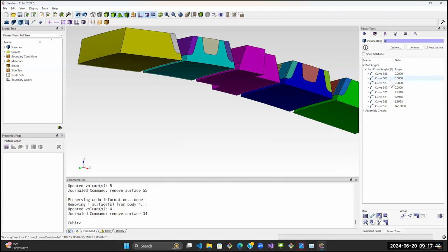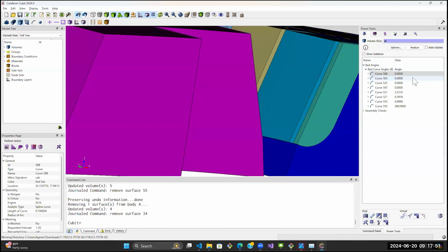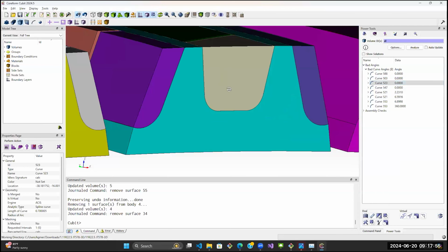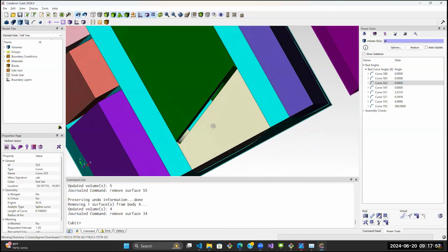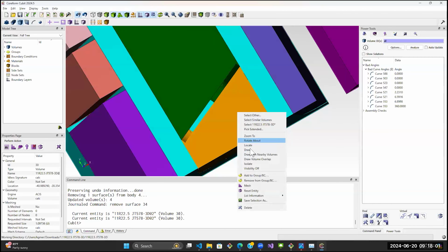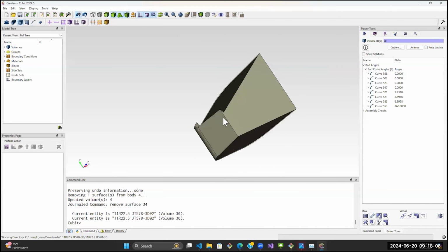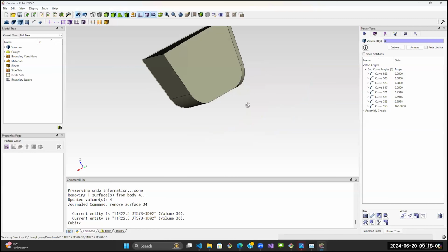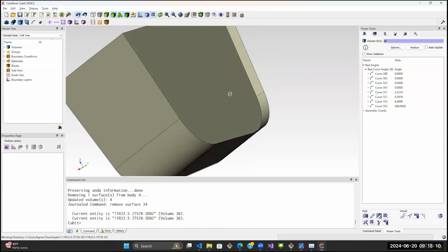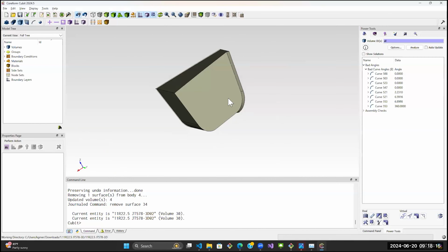But then there's also some bad angles that are 0. Actually, I think let's zoom to this one for this example. All right. So I look down inside that sipe, and there is something weird going on there. This is a small feature, much smaller than my mesh size, but it even comes down to like a 0 width thickness there.